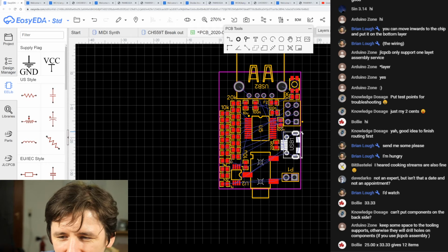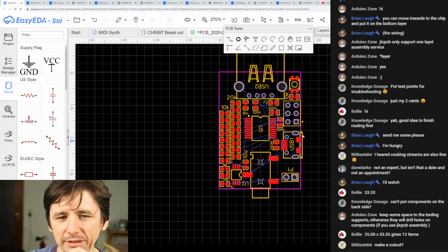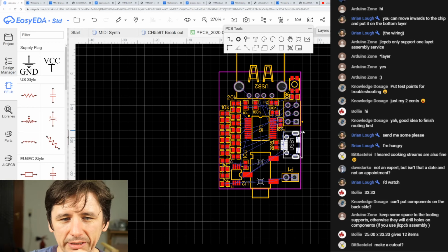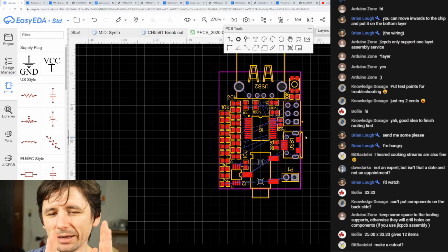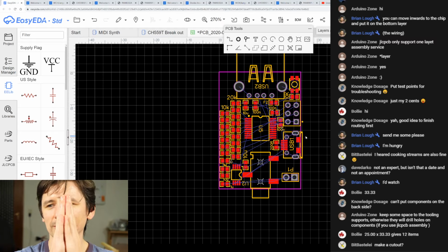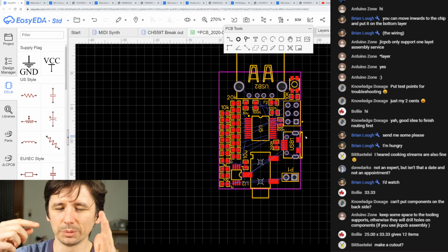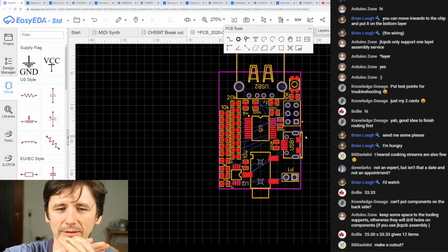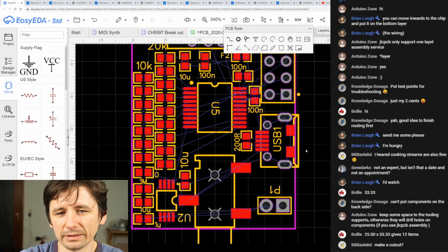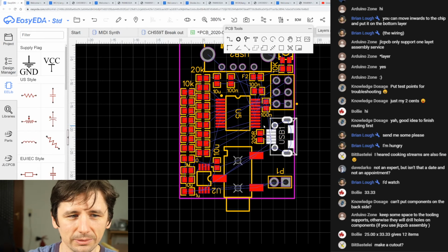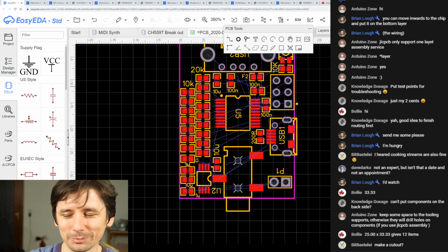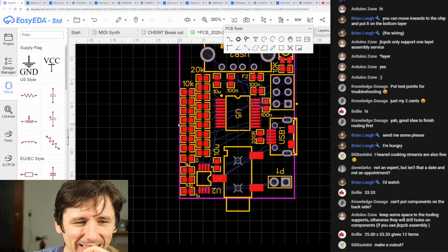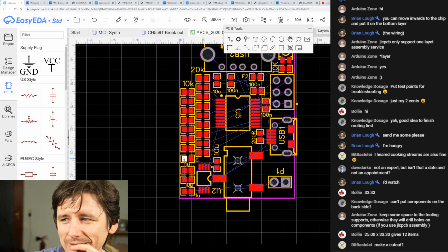Yeah, but I need a cutout either here, so move it further in and do the cutout. But then if I want to make a case for that, the case has to have a really thin wall to be able to put in the connector completely, or it's best to have it stick out like that. So I would need to have the cutout on the other side of the board because I want to penalize it, and that's not happening here. Do you see there's no space whatsoever?